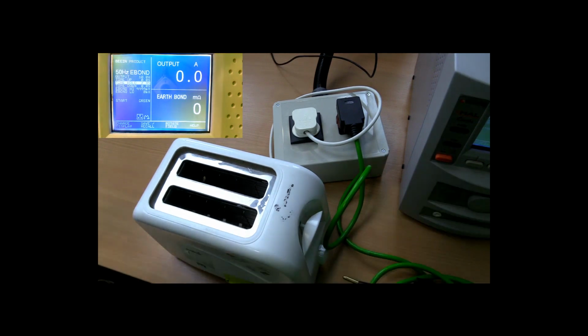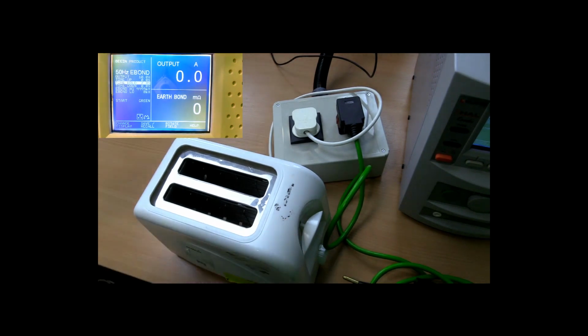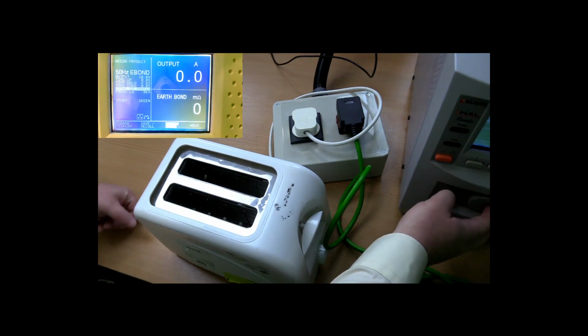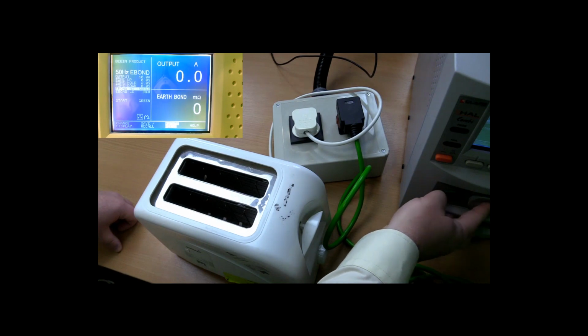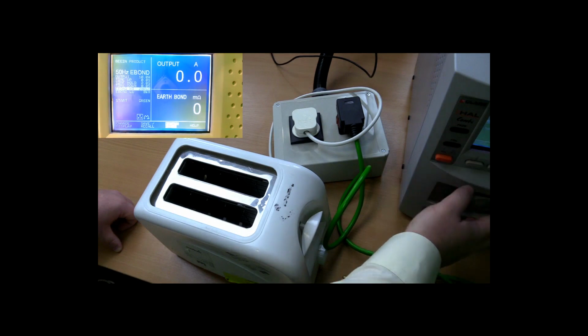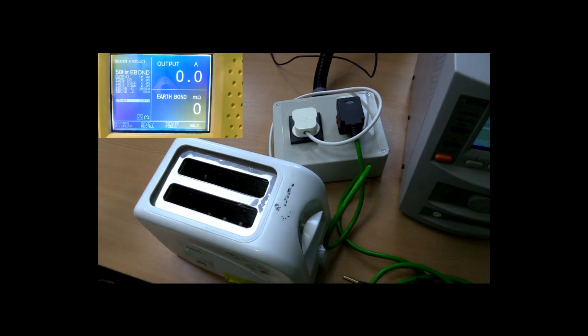Okay, and finally, the last thing we need to do is set our test limit. Now, the product itself has a supply cable, so according to the standard, we would be allowed up to 200 milliohms of resistance, or 0.2 ohms. So let's set ours to the 200 limit. Okay, so we now have 200 milliohms, and that's all we need according to the standard. So we're now ready to perform the test.